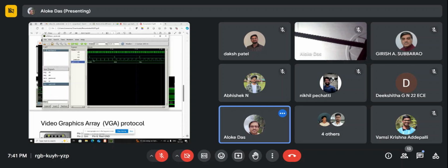See this signal. So enable, whenever I enable it, this uptime is latched based on this. This was first the uptime, then after this enable, uptime changes, the duty cycle changes here. Again there is an enable signal, after that uptime changes. See, so far I have not told you about the enable signal, PWM out, uptime, whatever. When I went to implement, I realized that there should be some enable signal.